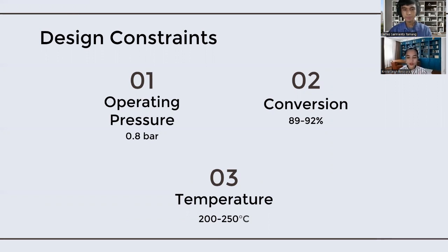of a leak. The oxygen used in the reaction can either be available as a highly pure reactant or purified air. The feed, cyclohexanone, a byproduct in a separate process, will be used for this reaction system and produced around 4,500 to 5,000 moles per year at about 85 to 90 mole% in a gaseous form, with other components inert to oxygen at a temperature of 200 to 250 degrees Celsius.